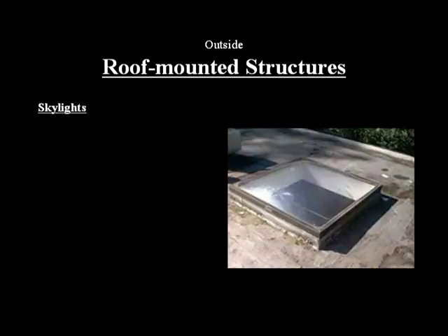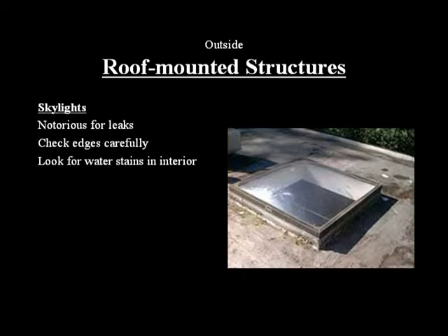Skylights add a nice ambiance to any room, but are notorious for leaks. Newer styles have an aluminum frame and plastic or glass panels and domes. Check the edges carefully, and look for water stains on the interior of your house.